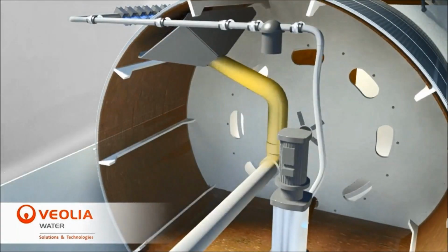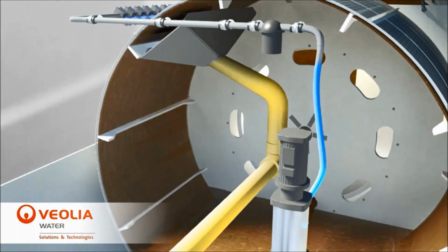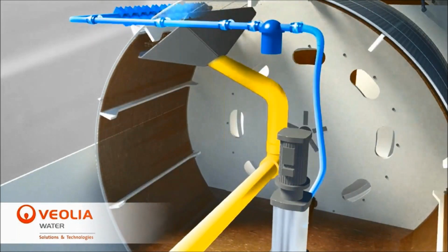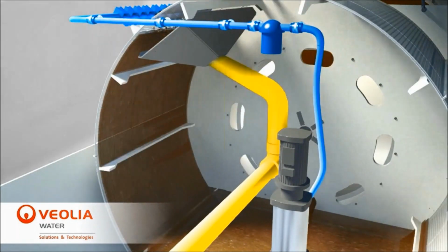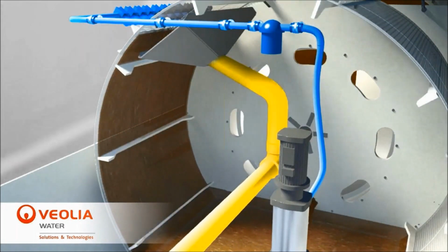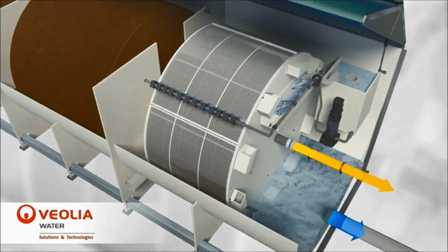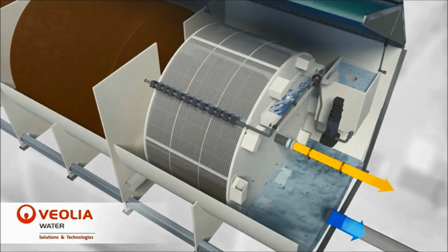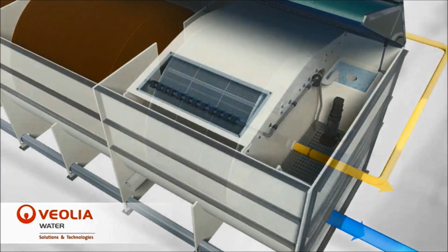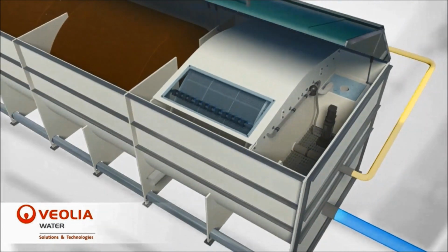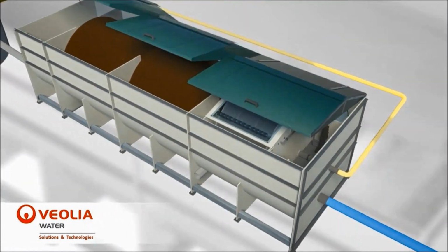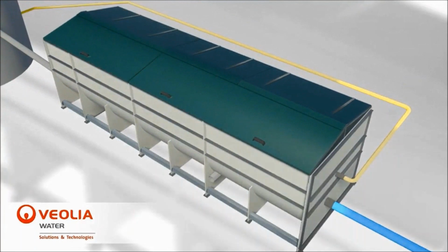The sludge retained on the filtering panels is backwashed into a gutter and is then extracted by gravity from the unit. In parallel, the clean water can be rejected directly into the environment or sent to a tertiary disinfection stage for reuse application. The unit that has been presented in this video has a capacity to fully treat the effluent from about 400 people equivalent in the Middle East.